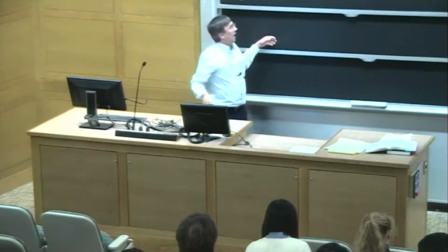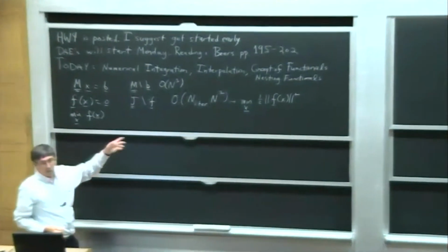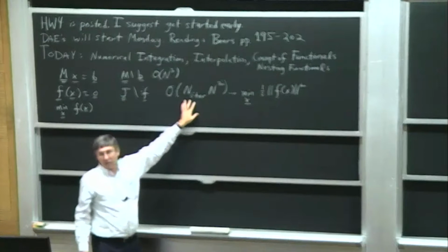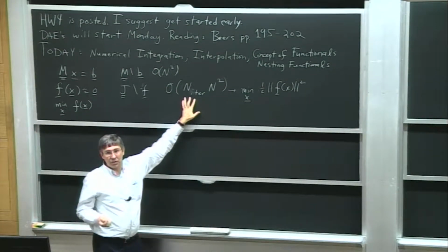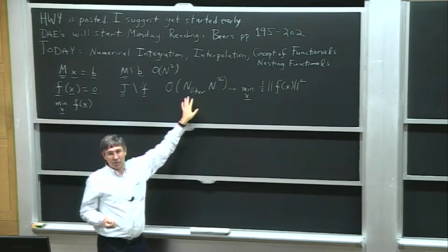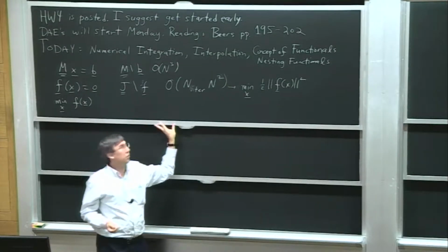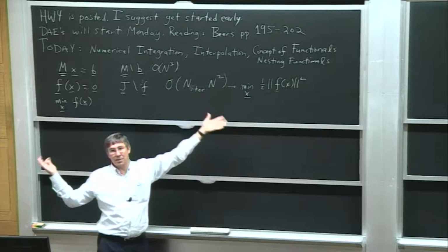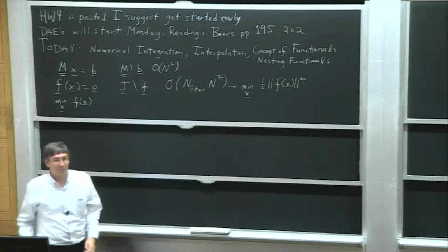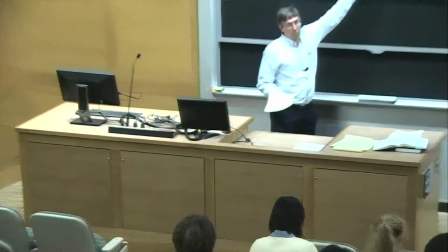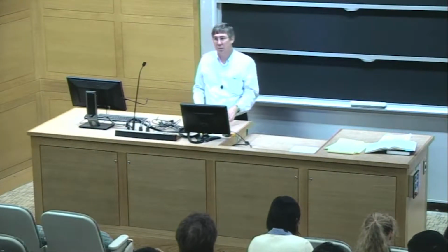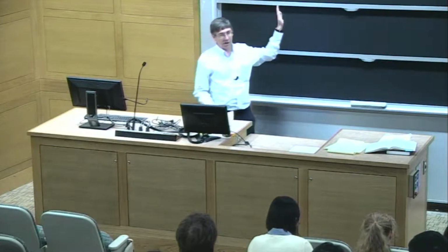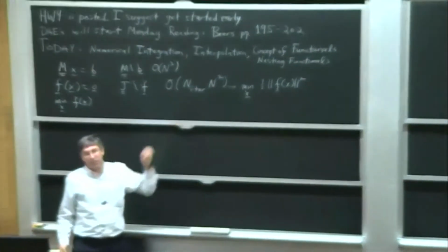Okay. And the same for these other methods. And then a lot of them get into how good the initial guesses are, because the number of iterations can get crazy. In fact, maybe it never converges if your initial guess is bad. So that can be a really critical thing to make this better, because you can't change n. How many unknowns you got is how many unknowns you got. But you can change the number of iterations by, say, more clever initial guessing. And that was the whole concept about continuation and homotopy and all this kind of stuff, trying to help reduce this number.